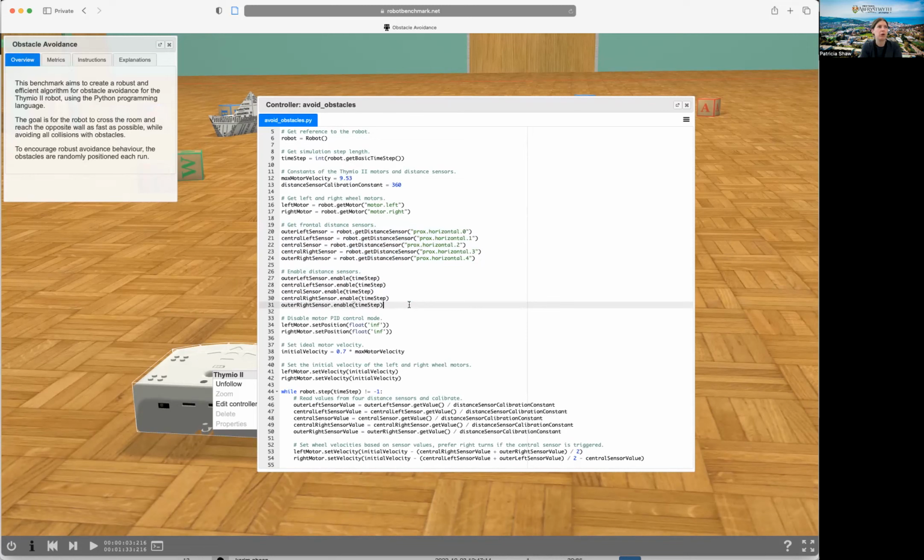And then I mentioned that it's using the velocity control for this one. Now, this particular robot language is slightly odd in the way that we switch from position to velocity control. By default, it is in position control, where you're defining a set point that you want that particular joint to turn to in order to move that joint. In this case, we really don't want to be setting positions. We want the robot to just drive across, and we don't know how far it's going to be driving. So we need to turn off the position control.